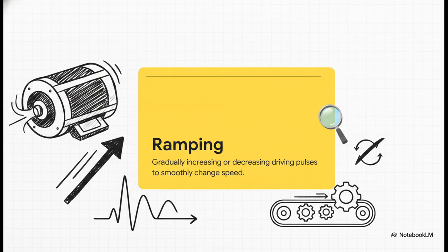And this ramping is very commonly achieved using V/F control. That's variable frequency drives, where the controller scales the voltage and the frequency together. This preserves the mechanical integrity of the entire load. No sudden jerks, no broken equipment.